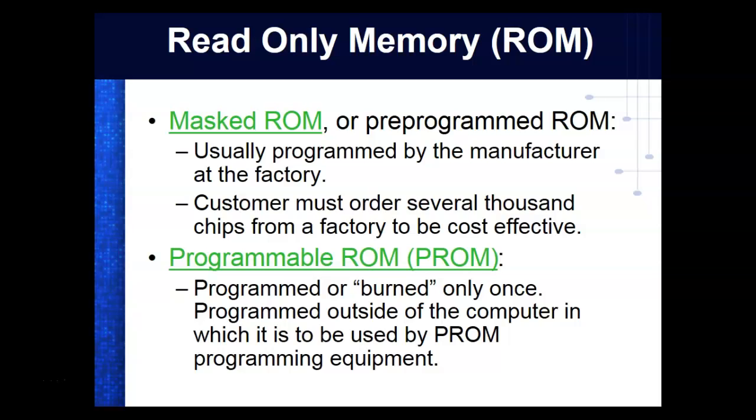Programmable ROMs. Programmable ROMs are burned. We program them. Literally, every storage cell consists of a little tiny fuse. If we didn't blow the fuse, it would give us a 1. If we blew the fuse, it would give us a 0. So we'd put this in a programmer, and we would literally send 1s and 0s in it, and it would pop fuses or not pop fuses. But these were one-shot, and it became known as burning.